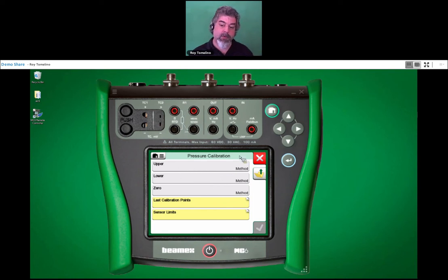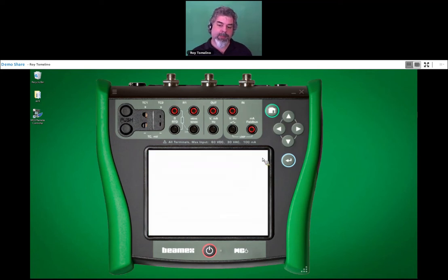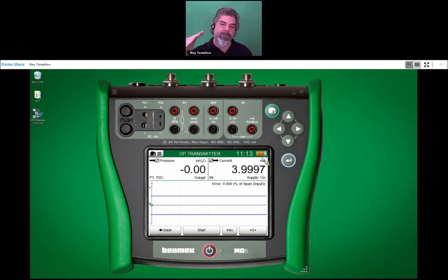Ned, do we want to do an upper or see how we are with the lower? No, I think it works the same. You would just pump it to 207, and it's going to read 207, so we'll just save time today and pretend we did it. How about that? All right. So let me hit the X on here. If the error would have been some kind of diagonal line, then I would hit the lower and the upper. If it's a flat line across, that means it's a zero shift, and we should be able to fix it by trimming just the lower.